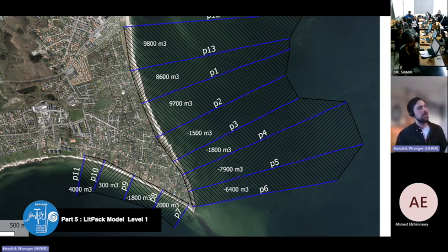So basically, all of these together meant that we decided that in the preliminary design phase for this project, there was no added value in setting up a coastline evolution module, that we could get the same answers by doing, let's say, housekeeping computations based on the outputs from the individual profiles. And of course that's more simplified because we just look at differences between those profiles. It's more simplified, and we don't know how this sand here would develop, would distribute, etc.